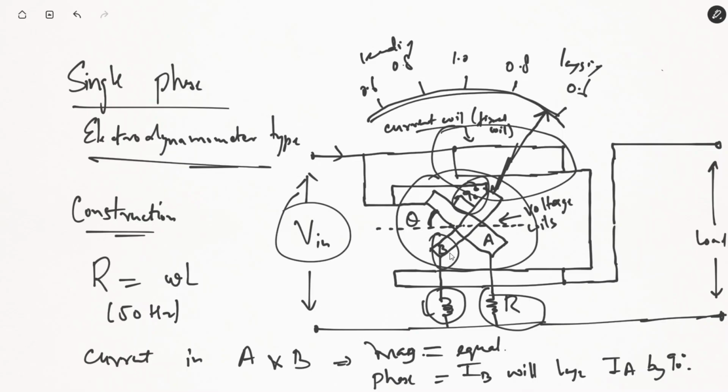Fine. The principle is that there is a pressure coil that's divided into two segments. One is purely resistive, another one is purely inductive, and you also have a current coil. So taking one by one, the current coil and coil A are both carrying currents. They will produce their own magnetic field. Coil A is movable, so when torque is induced on coil A, it will start rotating.